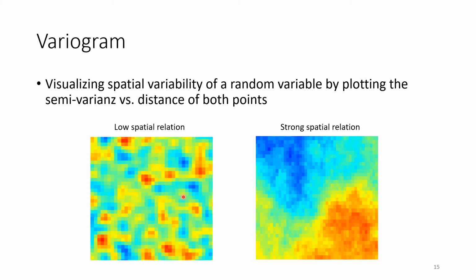Of course, this is a statistical distribution, but it represents the characteristics of your soil. I would still recommend varying those kinds of maps to see how much your material depends on those random parameters. But often you will see that, for example, if you have a small scale heterogeneity here, your flow path will be very tangled,